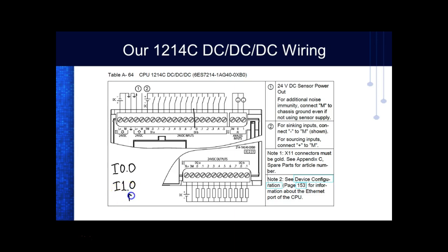So this is a big difference between Siemens and Allen Bradley. If I wanted to input a byte, I would go IB0. If I wanted to input a word, you'd use IW0. We wouldn't specify a bit. If I inputted a byte, it would be IB0, right? So Allen Bradley is a little different. Now the RSLogix 5000, which is the next version of Allen Bradley's programming software, I don't know how they address inputs and outputs. I'd have to go look.